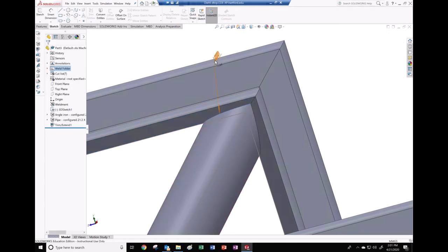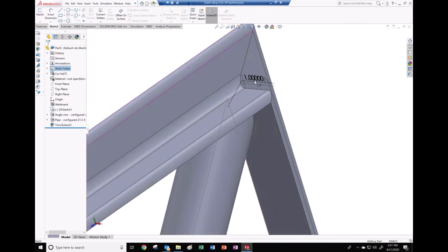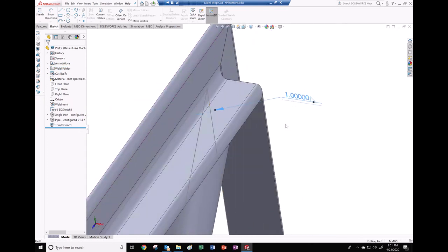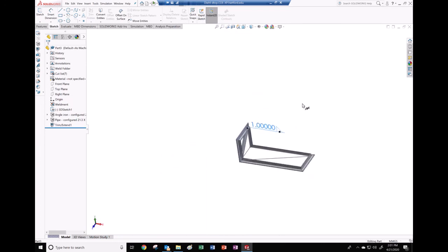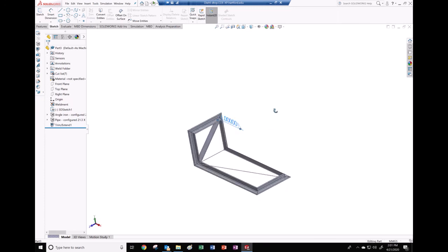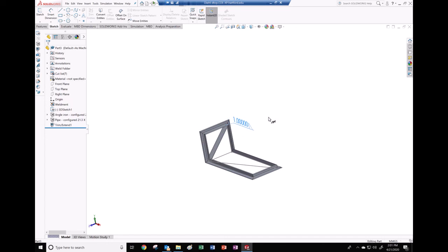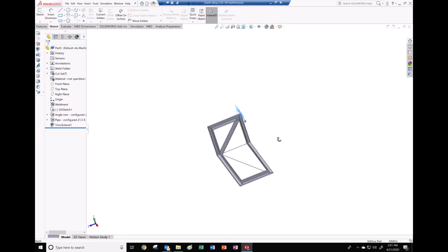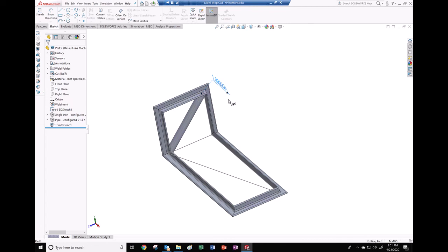And you'll see that there's a callout right here, and you could adjust what that leg height is going to be. Later on in the drawing section, this will show up, or there's an option to have it display this, and now you can designate. It can also make a bill of materials and tell you the length of a particular weld, so that you can budget how much it's going to cost for manpower to make this weld. So here was an abbreviated introduction to weldments.